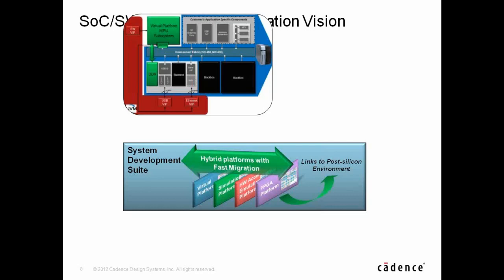You may want to do graphics benchmarks on a GPU, right? That's how people measure GPUs. Well, you could have a virtual ARM fast model, for instance, connected up with some of your SoC actually in a Palladium box, maybe the whole GPU, whatever IP. You can boot things like Android this way. Android boots in about 20 seconds. If the processor was inside the box, it'd take you like an hour. So suddenly you've got a huge speed up to get to the point where your benchmark starts.